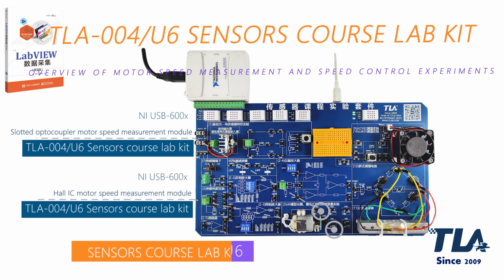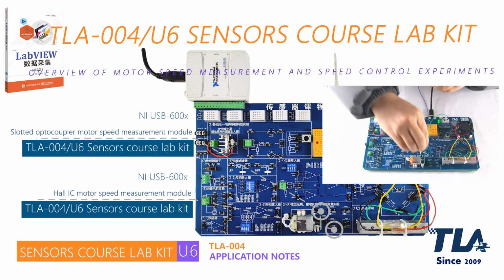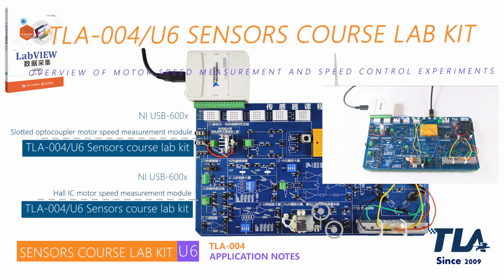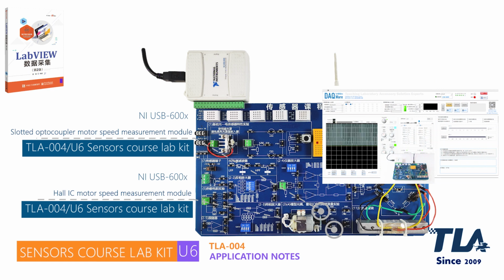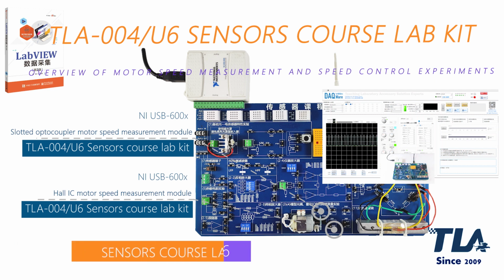Module 3 and Module 4 are experimental modules for DC motor speed measurement. Among them, Module 3 is an experimental module for DC motor speed measurement based on a slot optocoupler. Module 4 is a DC motor speed measuring module based on a Hall IC. The slot optocoupler is a kind of photoelectric sensor, and the Hall IC is a kind of magnetoelectric sensor. The 2 experimental modules share a DC motor, which provides the rotational speed signal for the rotational speed measurement experiment.